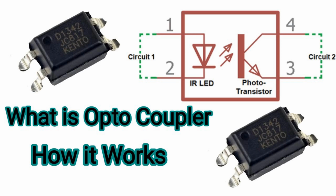Actuators. Actuators are devices or components that take the control actions generated by the controller and apply them to the system's inputs. They can be motors, valves, heaters, or any mechanism that can influence the system. Closed-loop control. Feedback control systems are often referred to as closed-loop control systems because they continuously monitor the system's output and adjust the control input to maintain or regulate the system's behavior. The feedback loop allows for real-time corrections in response to changing conditions.